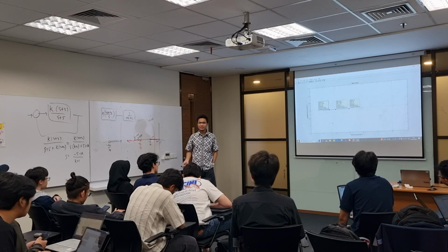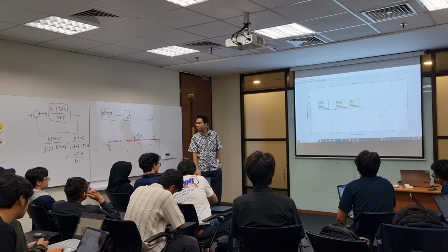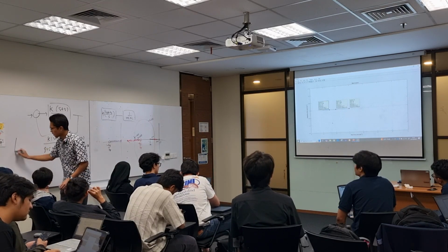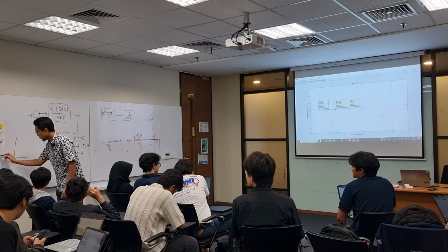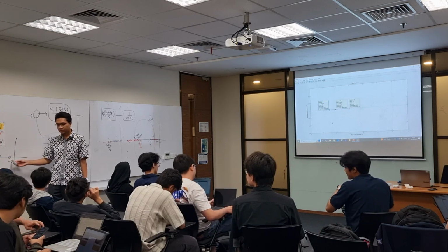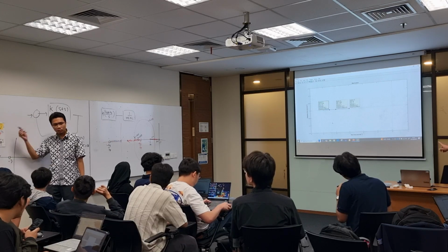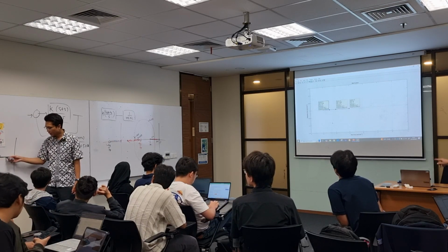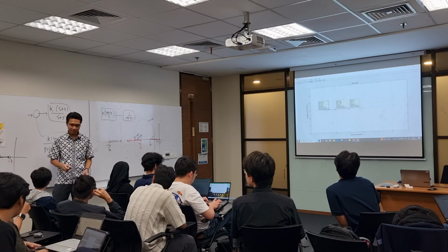But that's the situation. We have -3, and this is -5, open loop pole, open loop zero. The closed loop pole will depart from the open loop poles, and it will end at the open loop zero. So it will move from here to here.